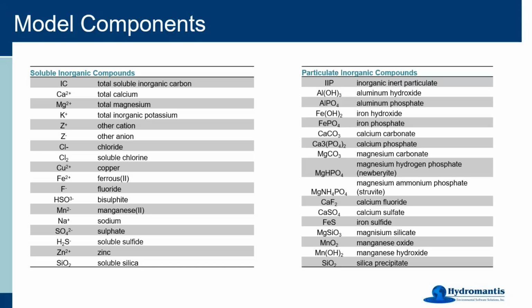The other part of it is that every water treatment plant system relies on quite a lot of precipitation reactions. As you add new chemicals, they react with soluble components and create some precipitates. So we are also monitoring those precipitates as their own components, so that when you look at the composite solids being produced from the system, you can identify what type of precipitates are there and what is the makeup of those solids.